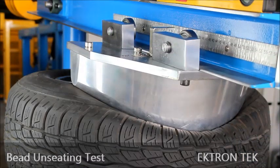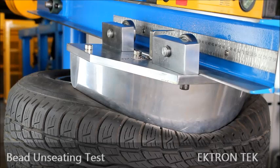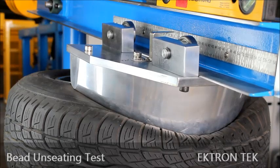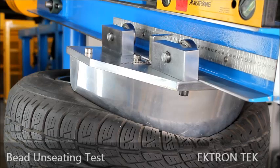Now we will unseat the bead. This will be detected by the machine and the piston will automatically return to the start position. The tyre can then be re-inflated and the next test undertaken.